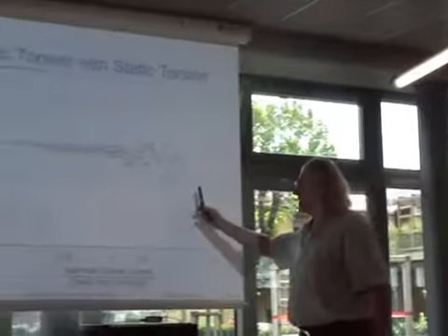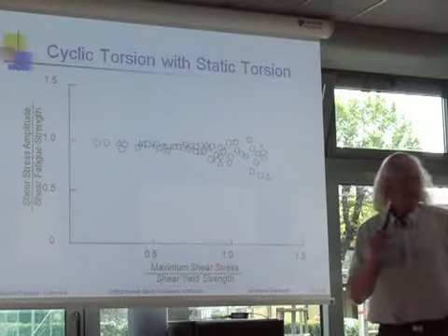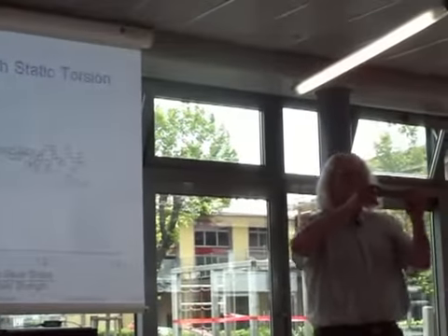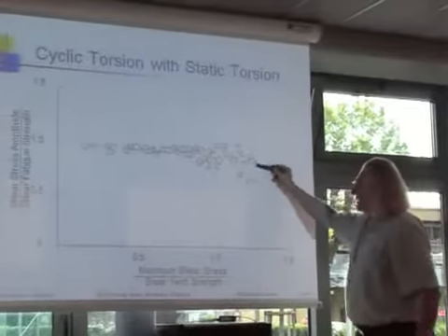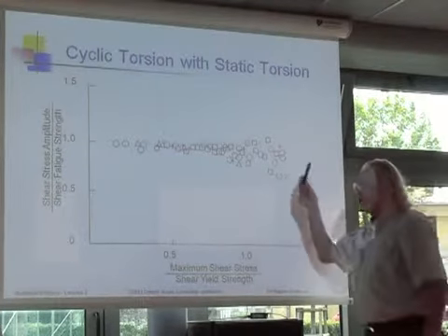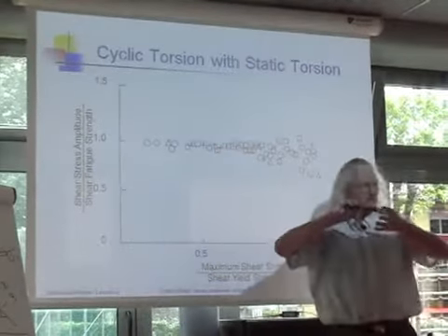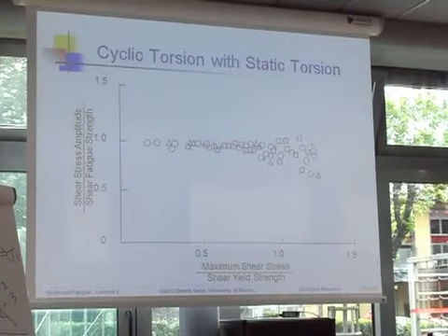And this data here is very unreliable for calculating the stresses. Why? Well, when people did these tests, they always reported the stresses from the elastic solution. So I test a round bar, and they take the torque times c divided by J and calculate the stress. Well, what happens when the bar yields? Of course, the stresses on the surface will not be what the elastic solution gives. The stresses will be limited at the yield strength. So I expect that this data incorrectly calculates the stresses from the elastic assumption. Nevertheless, we might conclude that the mean shear stress has no effect in torsion. No effect.